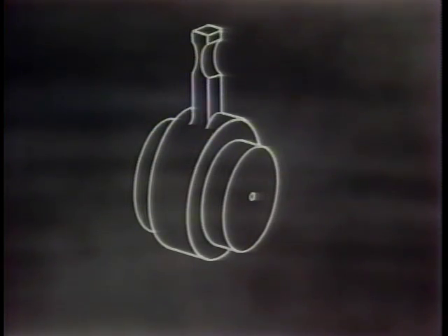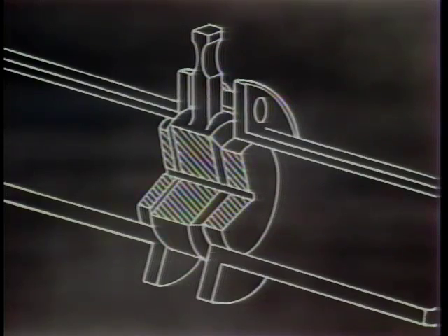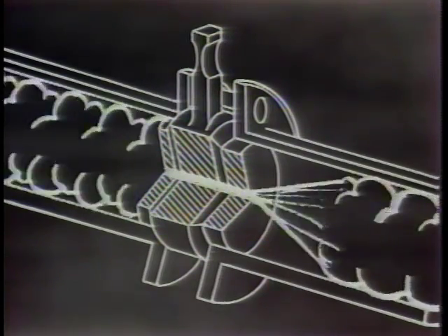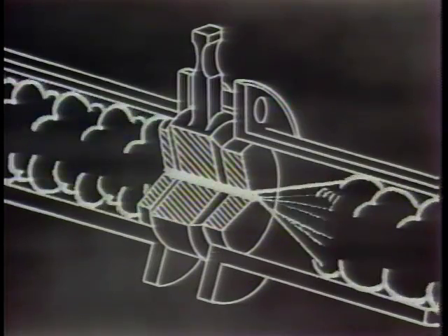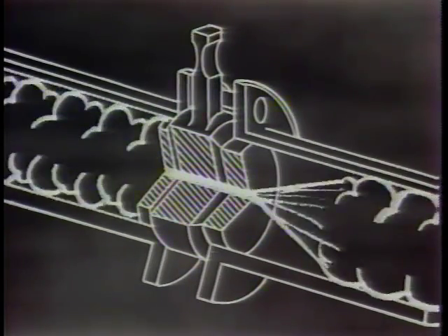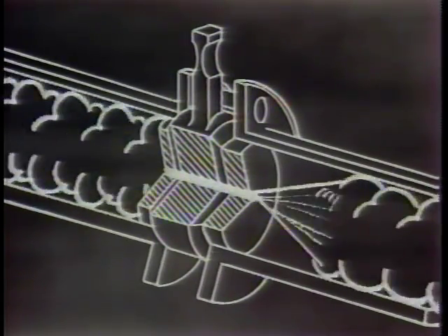Originally, orifice plates were used to reduce pressure. For any pressure and flow rate within a given diameter line, a hole or orifice of a specific size could be selected, which would yield a calculated pressure reduction. The problem was, however, both the upstream pressure and the downstream load were subject to change.